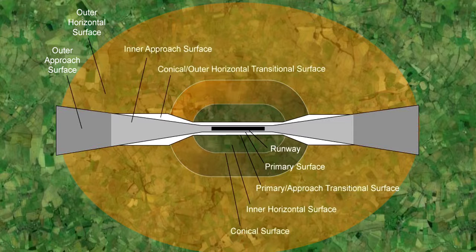A takeoff OIS will be a smooth plane with the base increasing in height as distance from the departure end of the runway, DER, increases. But for a non-precision approach OIS, varying profiles will apply from the final approach fix to the threshold.